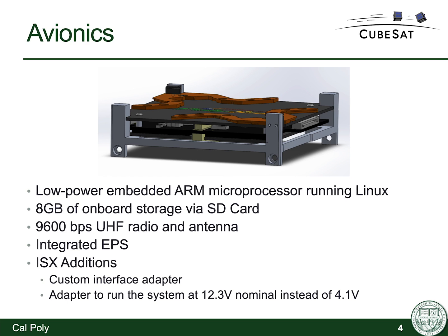There's a UHF radio that was designed in-house that we operated at 9600 bits per second, although it has the ability to operate at other speeds as well. There's an integrated electric power subsystem on the single board, so we don't have a separate board for all our regulators, for instance.